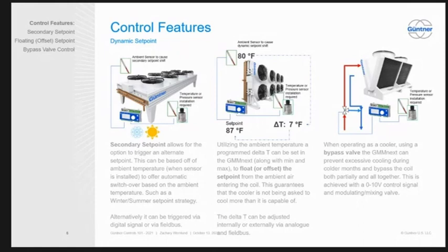So, can it do TD control? Like, can it do floating head pressure TD control in standalone mode? Yep, that's right here. So we have that also. You can do that in standalone mode, as long as you have the ambient temperature installed, because our controller needs to know what the ambient temperature is. You can offset the temperature by 7 degrees Fahrenheit, and you can set a minimum and a maximum.